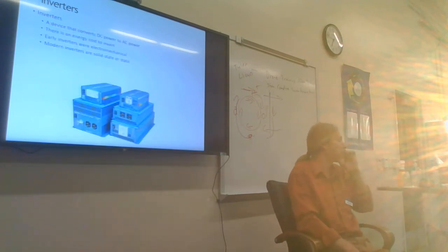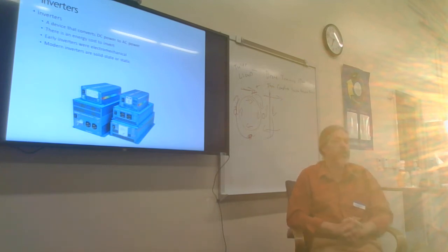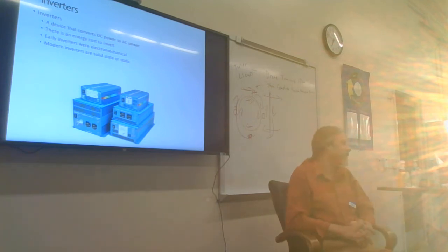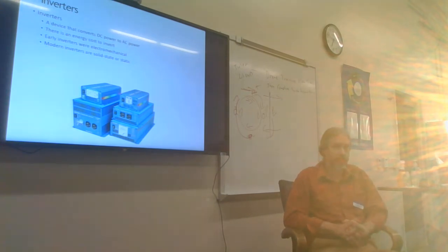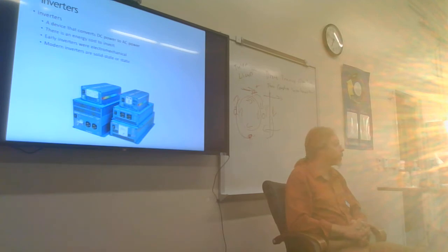All right, so inverters. Inverters are devices that convert DC power into AC power. There is an energy cost to invert, always. You're always going to have losses. Those losses are going to come in the form of heat. Early inverters were